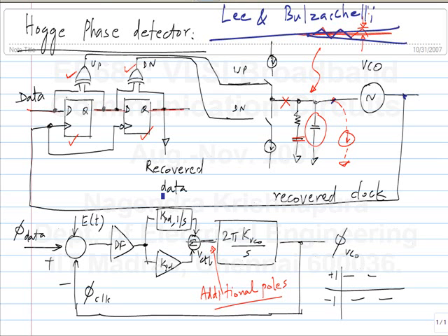Now, once you come up with a phase detector architecture, then you have to simulate it, or at least calculate it and see what is the jitter performance of it, what the bandwidth will be with that, what the phase detector gain is, and so on. What are the conditions under which it doesn't work, etc., etc. Okay.